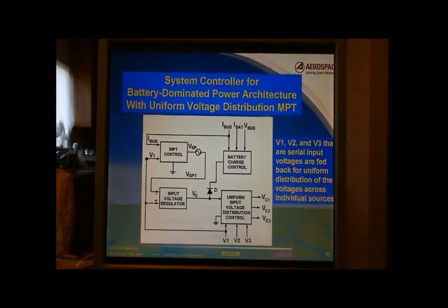The primary control signal VC is then dominated by the input voltage regulator working together with the maximum power tracking control. In this manner, during the maximum power tracking mode, these two control blocks, MPT control and input voltage regulator, work together.